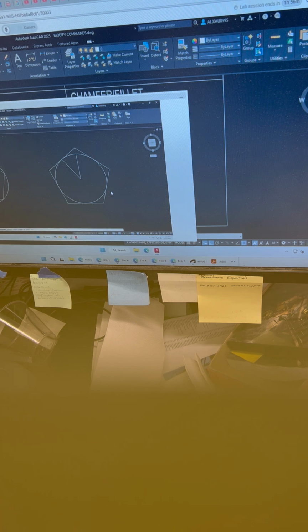All right? Pick anywhere within that little square to start. Oh, I'm sorry, I got a little off track. Notice the prompt. Always look at the prompts. They'll help you through, and I should have done that. It says enter the number of sides, and I was using 5. You can put in anything you want. It has to be at least 3, though. But put in however many sides you want, and hit enter.